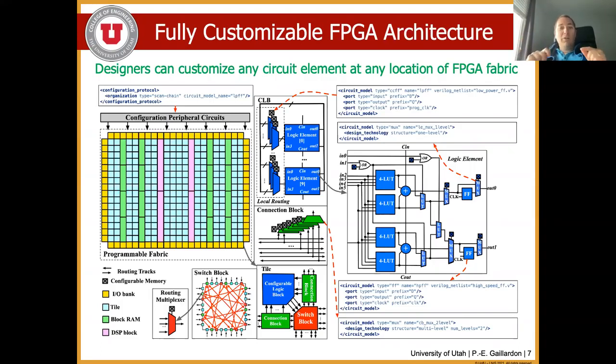It does not do all the heavy lifting in generating a generic FPGA architecture. It still relies fully on the designer to say how the FPGA architecture should be. And that is actually one of the secrets to get high performance fabrics. One of the common mistakes in other tooling is relying on behavioral descriptions. I have a LUT, and my LUT is supposed to work like that, and then give that to Design Compiler. Design Compiler will do something that is good enough, but you are not going to get the best performance.